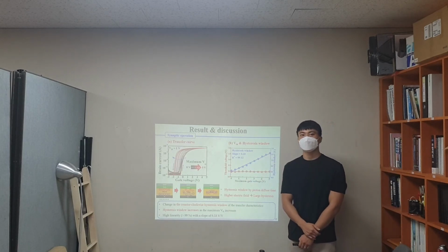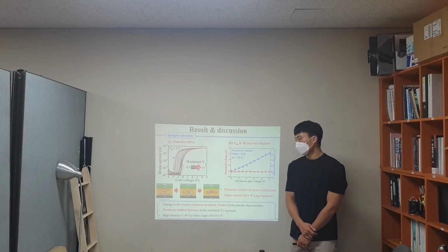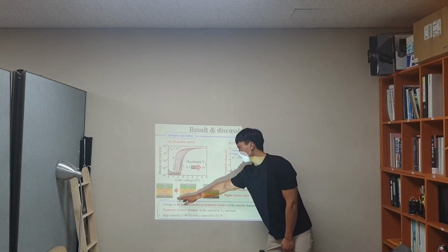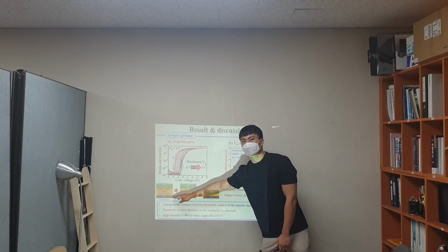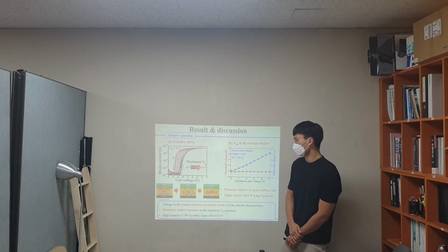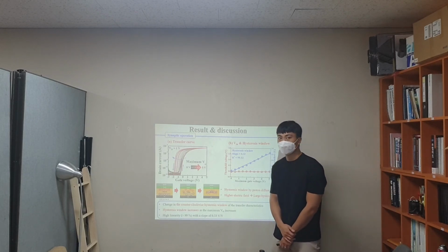It is related to the polarization of the dipoles in the tantalum oxide high-K dielectric and the migration of the mobile ions in the chitosan electrolyte, which induce charge carriers at the interface of the IGZO channel and the hybrid EDL.